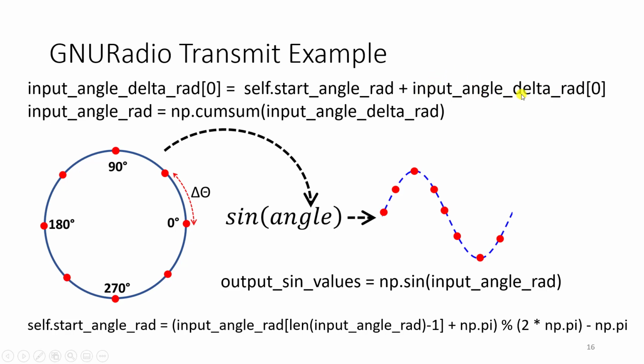of increasing this angular delta. So these values are the angular delta in radians, the instantaneous frequency of that chirp at any point in time along that line. And this is just a starting offset, which would represent, let's say, the lowest frequency. And so we form this line that we had previously, and then we sum those angular changes in phase, which is what we're doing.